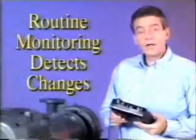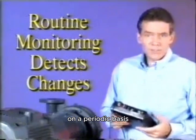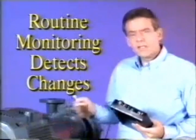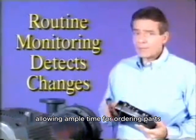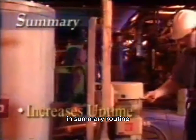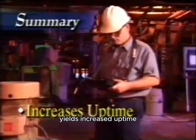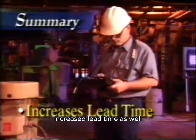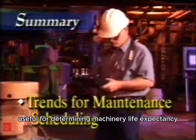However, when a machine is routinely monitored on a periodic basis, variances in the data indicate changes in the machine. These changes can be analyzed, and the problem can be determined, allowing ample time for ordering parts and scheduling a downtime. In summary, routine periodic data collection and analysis yields increased uptime, decreased maintenance and repair costs, increased lead time, as well as a trend useful for determining machinery life expectancy.